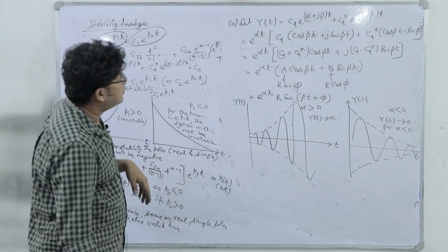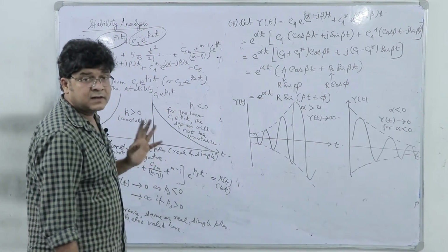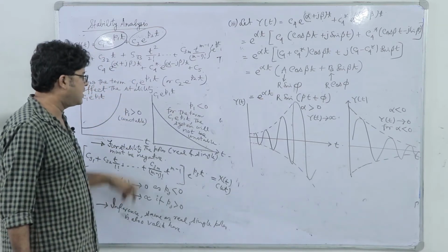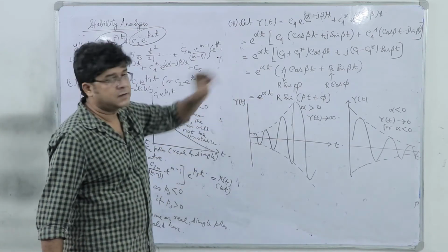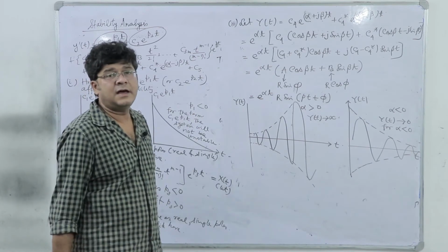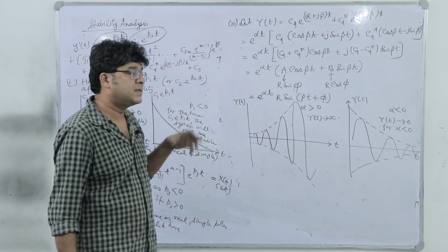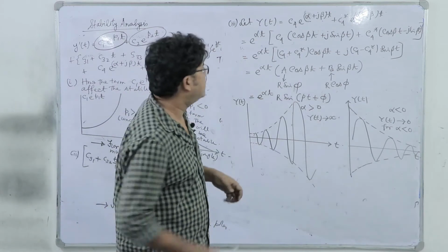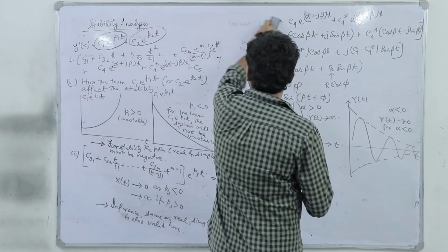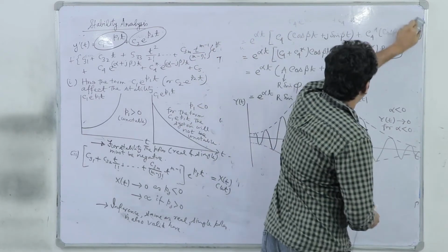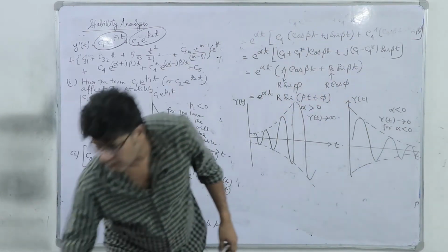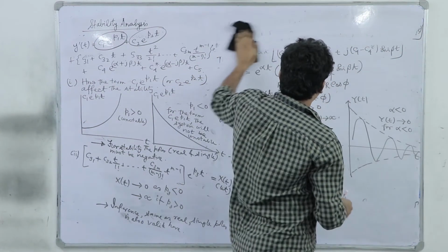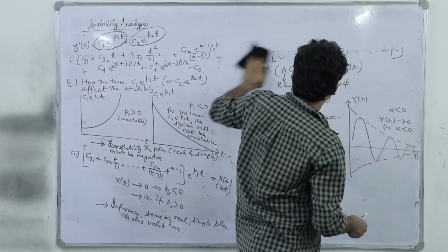So what will be our general conclusion? We have explored the real single, real multiple, and the complex conjugate poles. And the conclusion is that for stability, the real part of all the poles must be negative, right. So that we derive from this baseline BIBO criteria. So let us first summarize what we have got, and after that we will proceed.